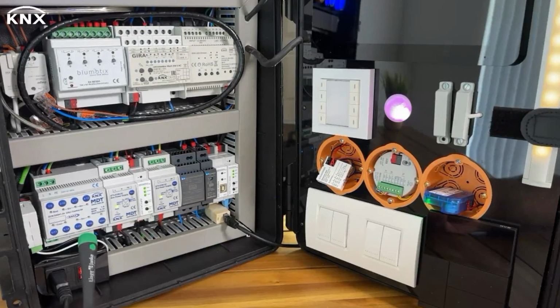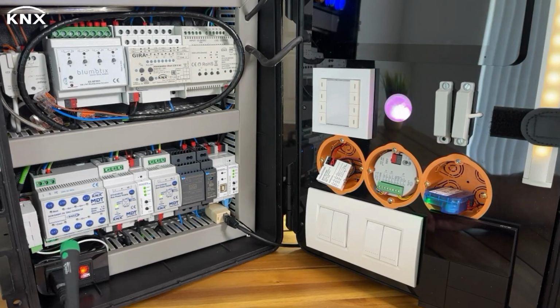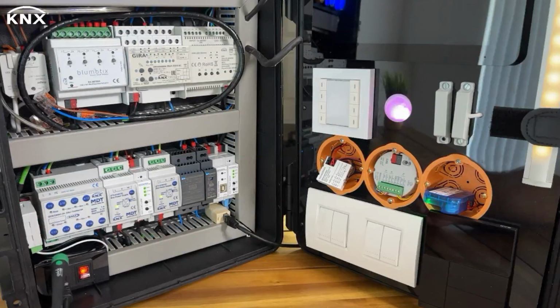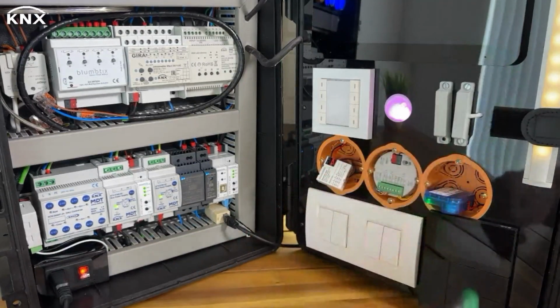For example, if you are in the US, you need to go for Siemens. Siemens is the only manufacturer today so far that has KNX dual listed line devices in the market. On top of this we have the line, neutral and the earth, and down here we connect the DALI bus. The DALI bus goes all the way to all the DALI drivers.